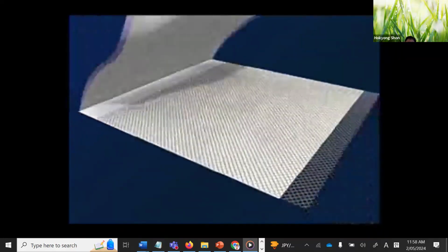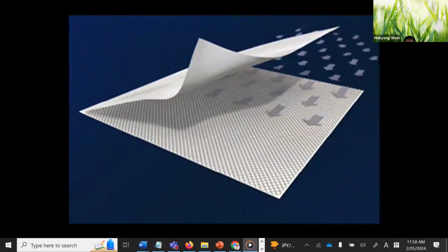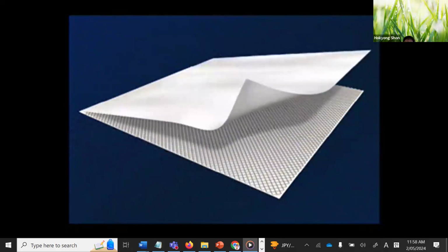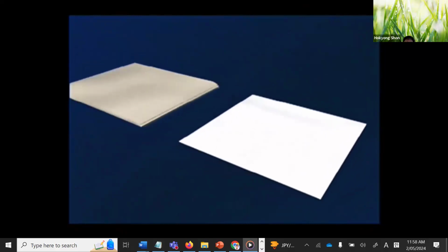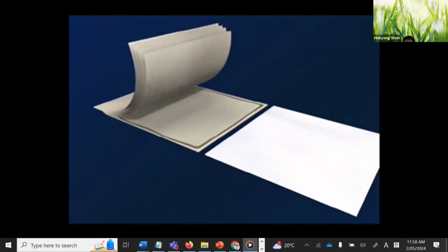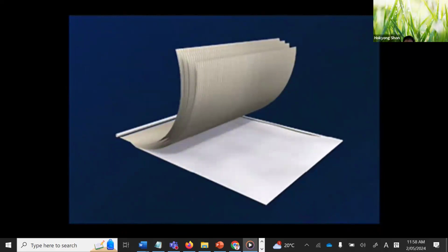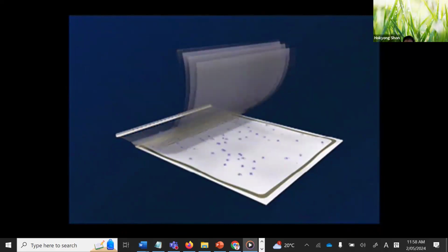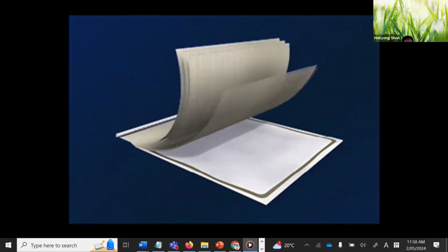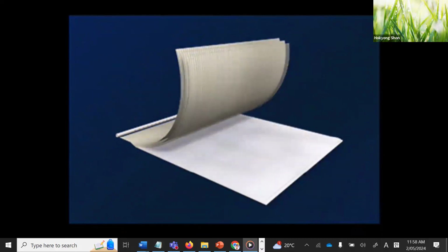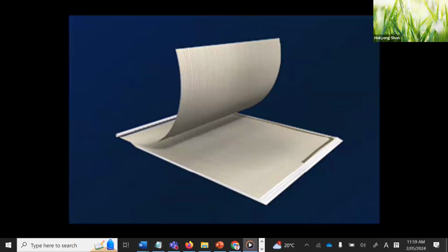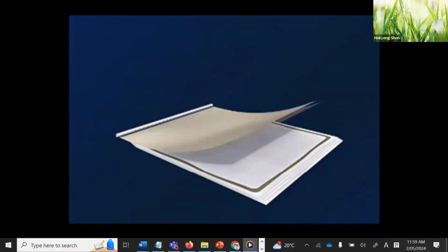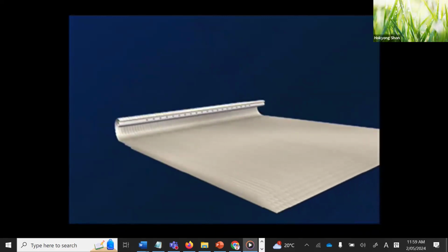The membrane flat sheet is then combined with a sheet of feed channel spacer. This provides turbulence and creates space between the membrane sheets to allow uniform flow of the water to the entire membrane surface. The leaves of membrane and feed channel spacer are then combined with a sheet of permeate spacer, which provides open flow channels for the permeate even under high pressure. The leaves are glued along each of the three exposed sides, and then rolled around the coiled tube.